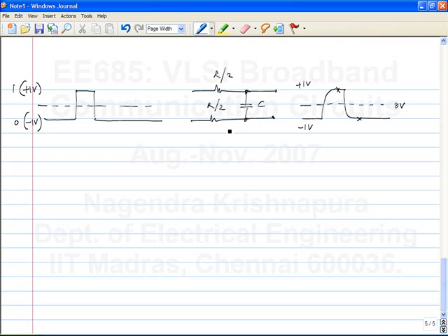But what happens as we increase the time constant RC? It can do this, okay? If the time constant is large enough, it can do this where it has barely, the input goes from 0 to 1 and back to 0. The output starts from a negative value because it has reached steady state with -1 volt, and then it barely reaches the positive values and comes down. And it can be even worse in that it may not even reach 0 volts.